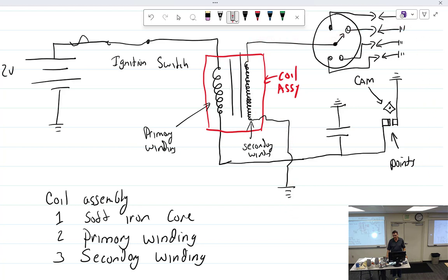Okay, so about this 20,000 volts: you're only going to build up as much voltage as you need to make the current flow. So if this gap is basically non-existent, if we didn't have a gap right here, it wouldn't build up to be all that much. It would just dissipate itself through the ground. Yeah, or any gap in there, or the distributor. And now if you take the spark plug gap and start moving it out, the voltage will build up until it can flow.